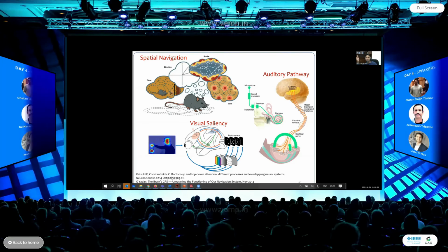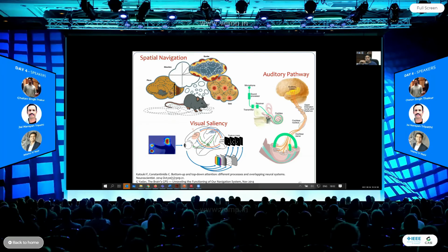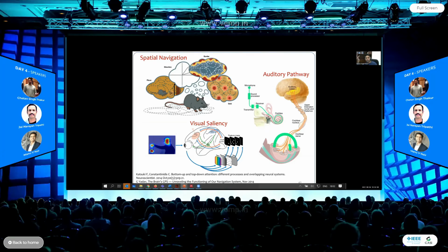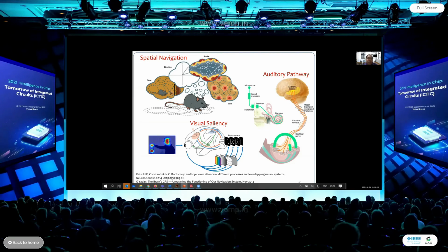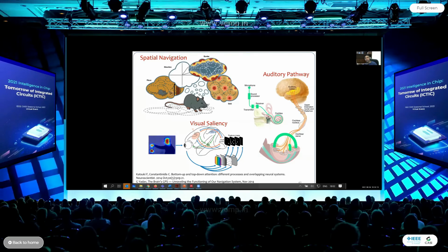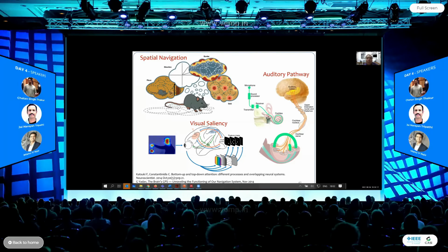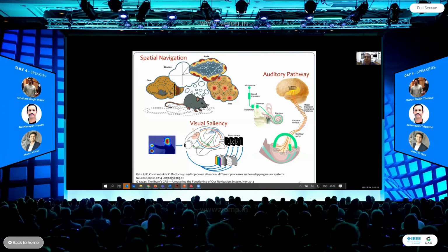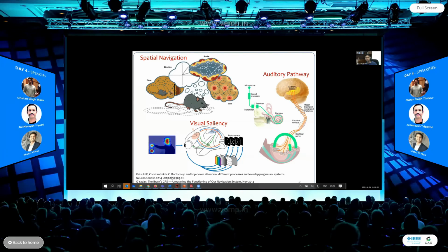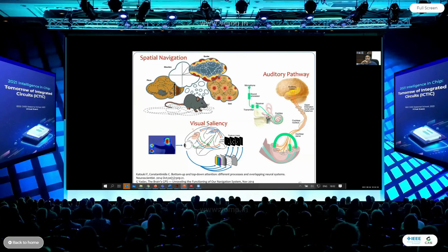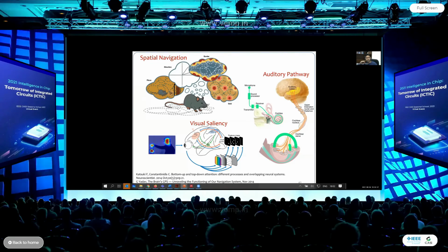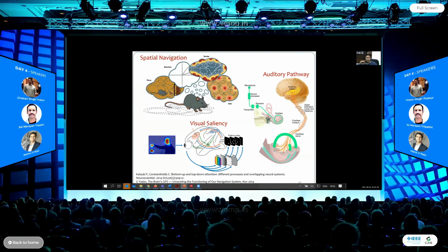Because you always need some kind of pre-processing for sound. People use MFCC, but MFCC is very hard to implement in hardware, because you have a filter bank, then a log, then a DFT, and then again a log. But here it's a biological processor. It works pretty nicely and has performed really well, and that's what we have been using. We have used it in a couple of our papers. If they are interested, they can take a look on the website.